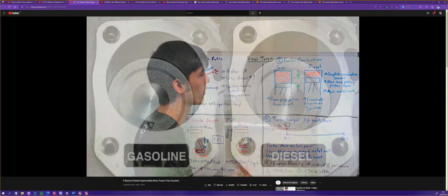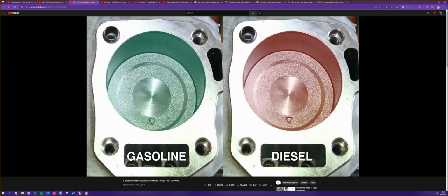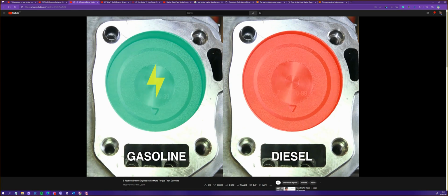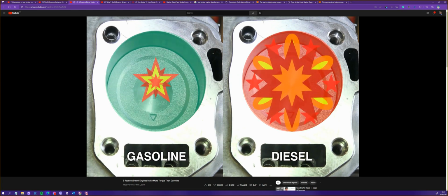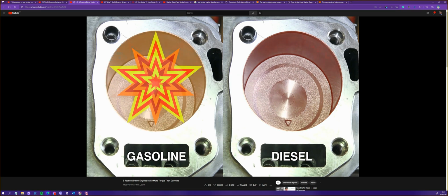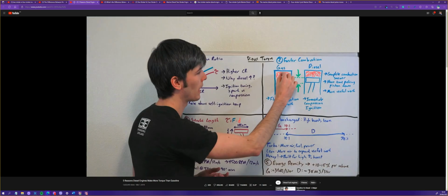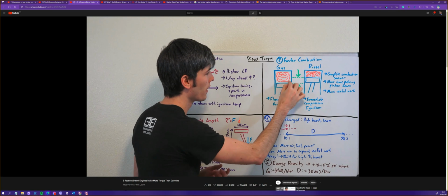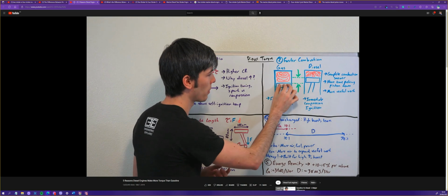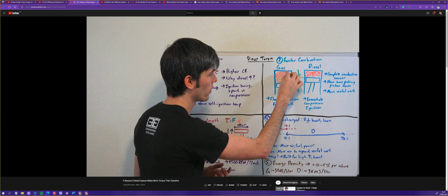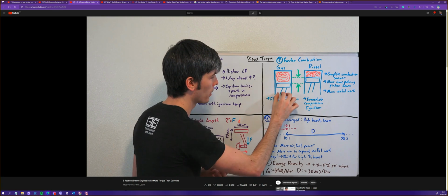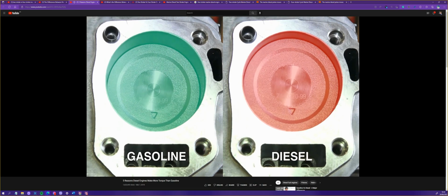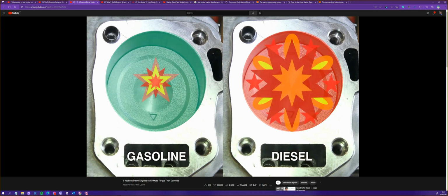And the result means that with the diesel engine, there's more time that fuel is spending pushing down that piston versus the gasoline engine, which translates into more useful work and more torque produced. So in the gasoline engine, if you still have combustion occurring when the piston's way down here, that combustion is only going to be pressing the piston down for a short duration, versus if it happened up top, it would have pushed down that piston for the entire duration. So you want that immediate compression ignition property of the diesel engine to maximize how much torque you produce.